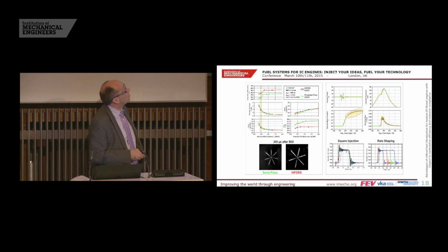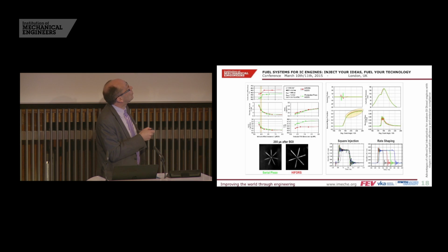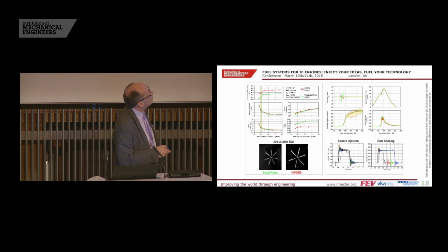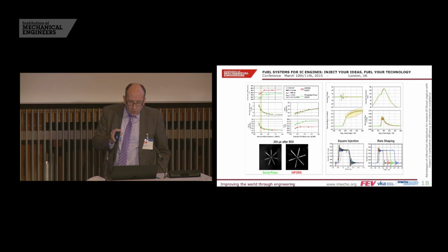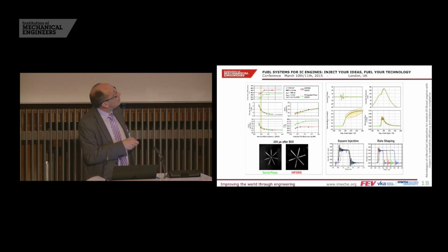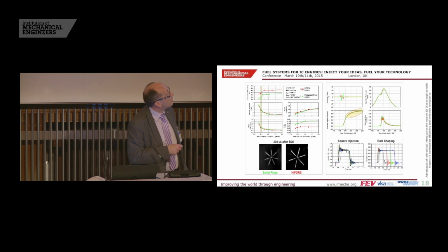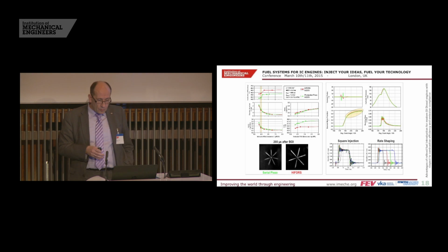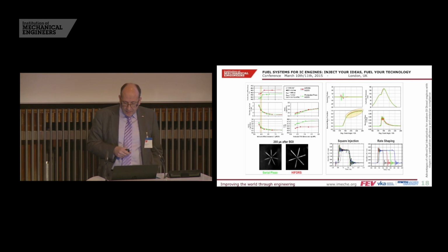Going further, the next load point is the higher load point. You see here, once again, more or less a similar behavior, so quite similar emission performance with a slightly better acoustic behavior of the injector, and we also identify roughly 1% better combustion efficiency of the high force injector versus the classical or production counterpart. And if we go into some thermodynamic analysis and post-processing, we see that this is mainly coming from the second phase of the combustion, where we have somewhat faster fuel conversion than we have with the classical counterpart.